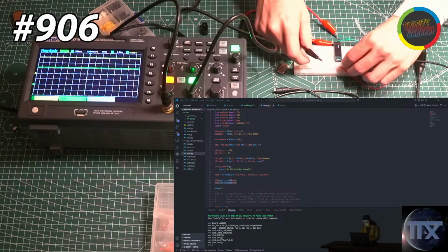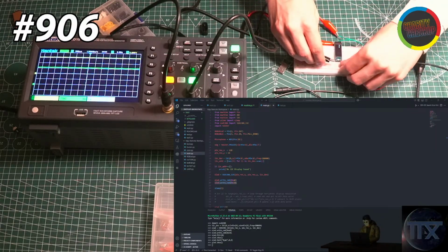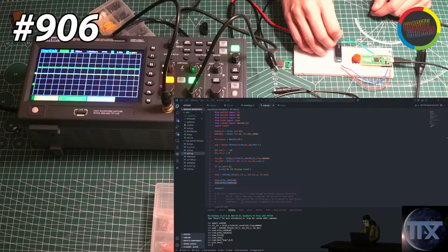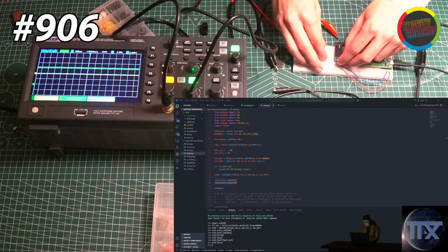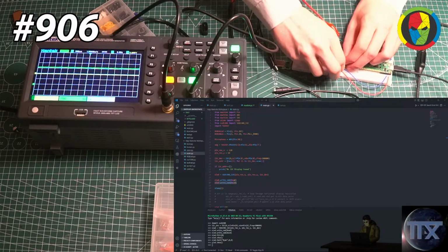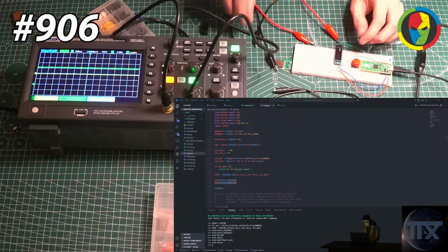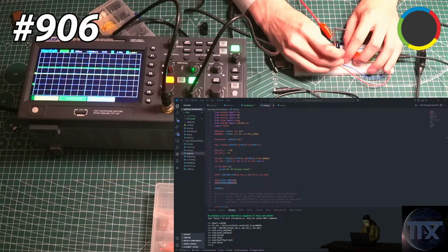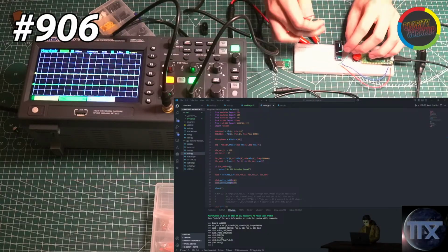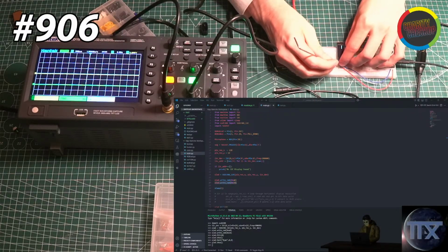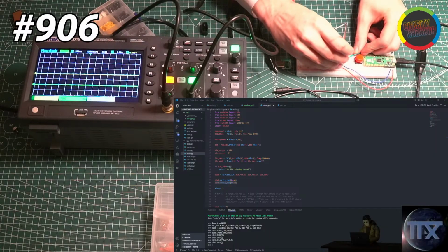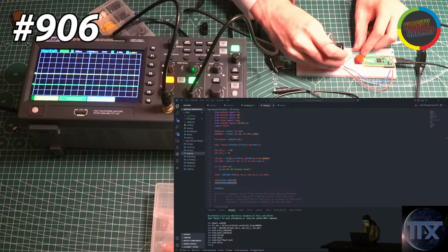But you do want to connect the screen end. You're not going to be able to, because the screen usually sends back its I2C address. If you connect it this way, you will see the microcontroller communicate on those two wires, but it's just going to stop real quick. If I want to see I2C, I would constantly scan the I2C on the microcontroller, and then you can watch it, read it.